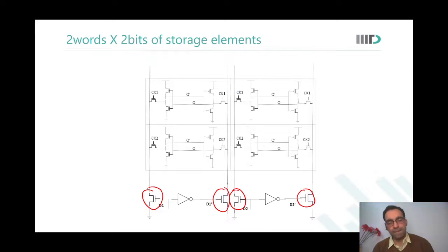Sir, when we were removing those clock transistors, when you were saying only one will have a clock out of 1024 transistors, but we don't know which one it will come on, so we remove them? No, we are removing it for everyone. That is why we removed it for everyone. Okay. We didn't remove it only for one cell. We removed it for everyone. Okay. And we said we were bringing in a sizing constraint now. Yes, sir. Okay.